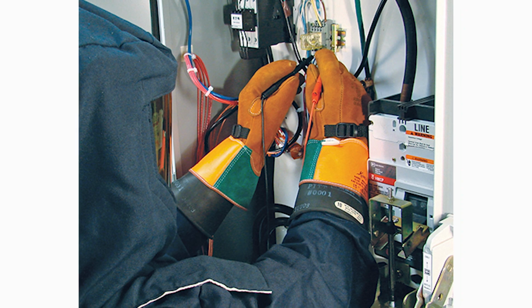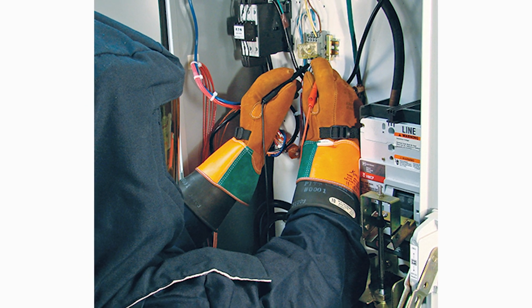And why that's important in an arc flash study is when I take the fault values from the short circuit and I take the timing from the coordination study, those are two primary factors that go into the arc flash analysis. So typically you'll see an arc flash study combined with a short circuit coordination from that perspective.